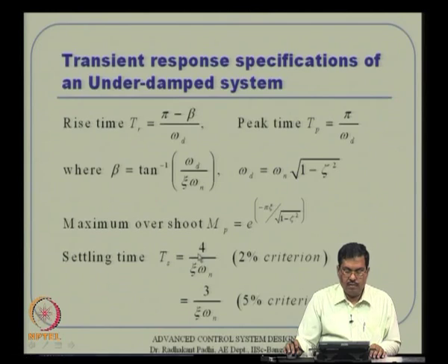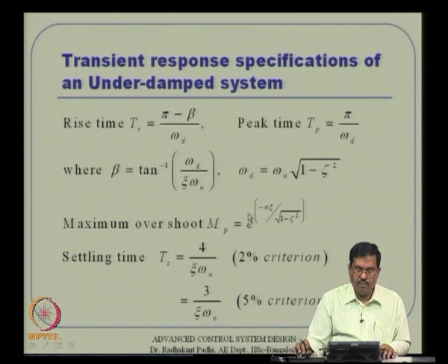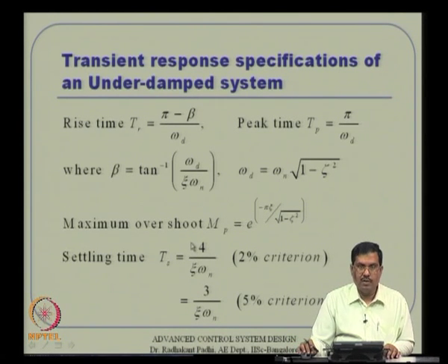But for second order systems, you have to remember at least one more thing. So probably percentage overshoot is another thing to remember quickly. Once you give us how much percentage overshoot we want and how much settling time we have, we start our design process and can design a control system which will satisfy these time domain conditions.